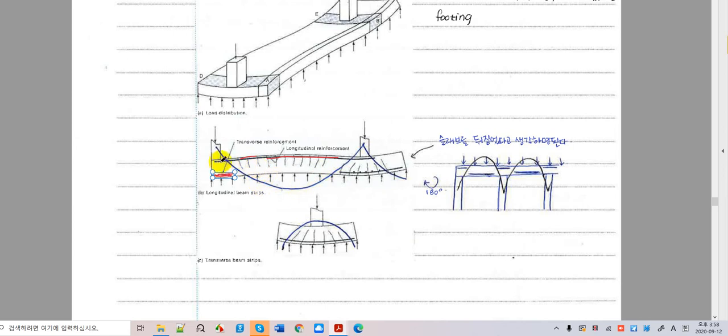But we just extend it to the end. To me, it's a minor error that occurred right there. The author somehow extended this to replace this reverse, but it's not. So we just follow the mechanics and structural analysis principles. Then this rebar should stop somewhere here, and this rebar should stop on there as a revision. Same thing here. So this is top, right? This is top because this is a moment, negative moment or positive moment or whatever, according to the definition.